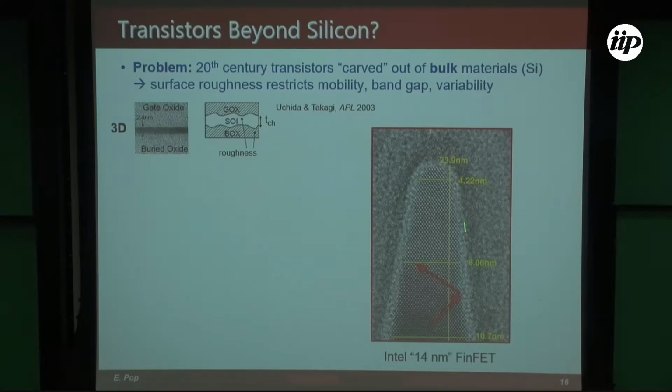But look at this. This is the 14 nanometer Intel FinFET. This is a cross section of the FinFET transistors in my laptop right now. This laptop is 1 year old, so it has these things inside of them. And you see that this thing is 8 nanometers wide. These are little fins of silicon coming out of the wafer. Current flows in and out of the plane. You see every single atom in there, which is mind-boggling. It's very, very cool, to the fact that this is actually commercial and we can buy it, right? And there's billions of these on the chip.